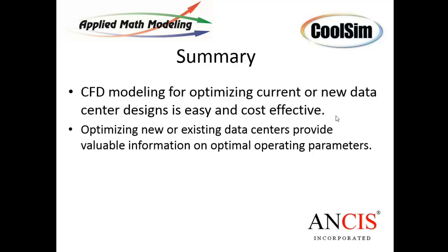Yes. We're modeling the flow inside the ducts, and you saw in the first model that Dana had stepped the duct down in size. We do full CFD calculation inside the duct, and so those sizes do change the velocities and the pressures inside the duct. So if you have a duct header and you disable different AHUs, air handlers, the model will show how those ducts flow data. It's fully accurate with respect to modeling the interior of ducts, and it does it quite nicely.